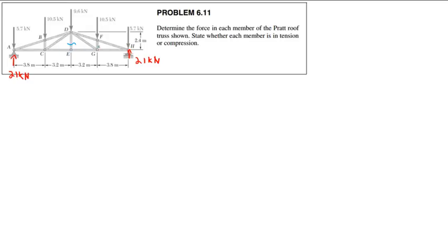I have two collinear members, CE and EG, along a straight line, and there is a third member going into that joint without anything to resist it. So if there were any force in member DE, there would inevitably be some vertical load on this joint, and because these are purely horizontal, there would be nothing to resist that load, so the joint would be moving. So therefore, this has to be a zero force member.